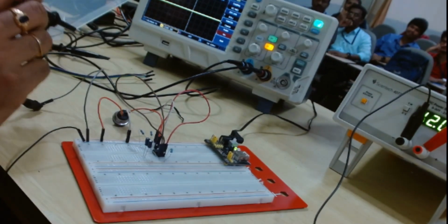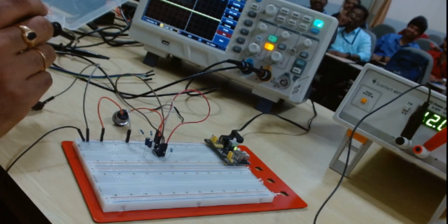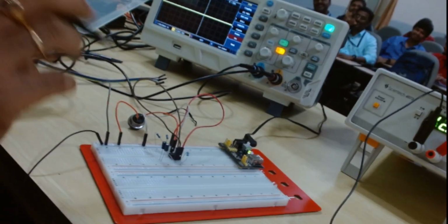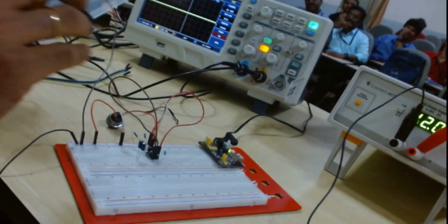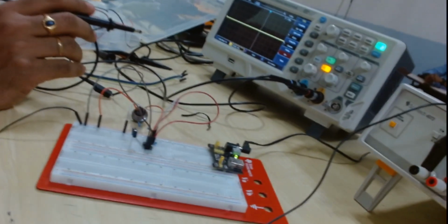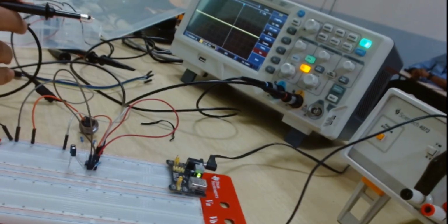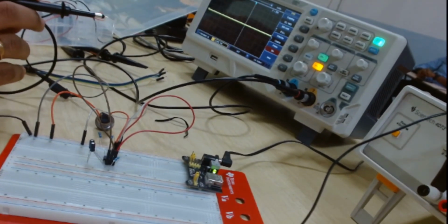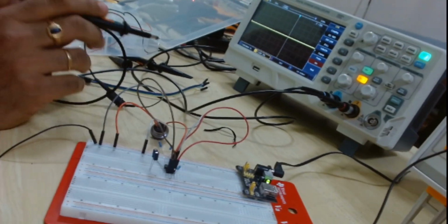See, this is the first one. There is a loose connection here, so power was not coming, so I was not getting 5 volts. So I have made my connection. I have not added the transistor and the motor for the time being. I have just made the monostable connection, because divide and conquer. First I will see whether my monostable works, then I will add the next circuit.